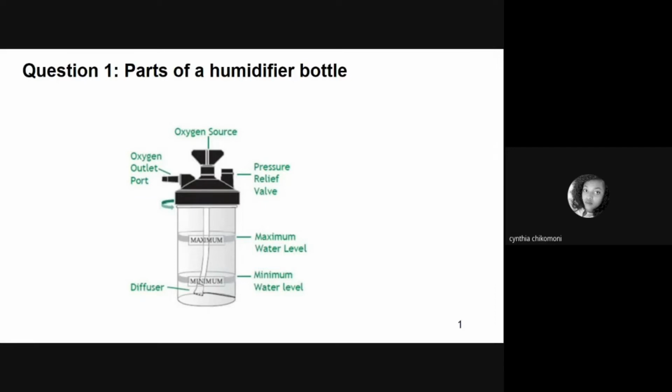One is to help stop the growth of molds, and mold colonies are far less likely to be present in distilled water. Number two is that tap water contaminates the humidifier bottles with calcium, salt, and magnesium found in the tap water, which tends to block the air outlets in the diffusers.